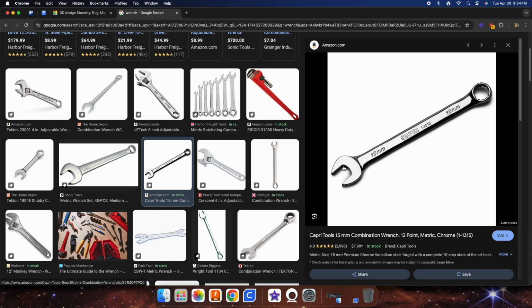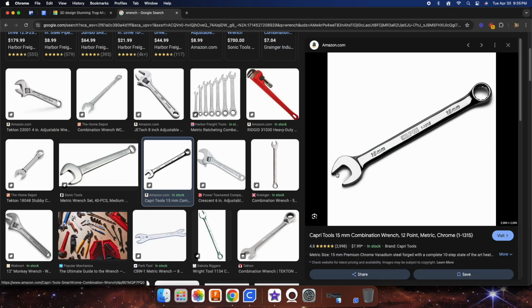And then how do we do this? The wrench here just has a little part that's cut out. So we can break this down into big rectangle, circle, and then square cut out of it. When you're breaking stuff down into shapes, don't forget that you can cut things out. It's not that you can just add them. Like, it's not like you have to add a crescent moon shape for this part because there's nothing there. No, you can subtract material in the design.